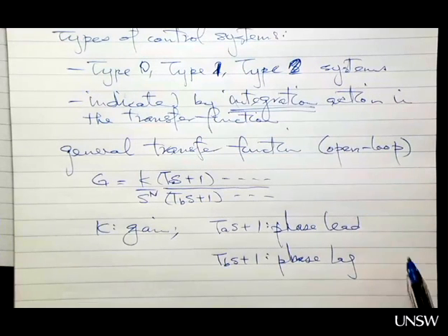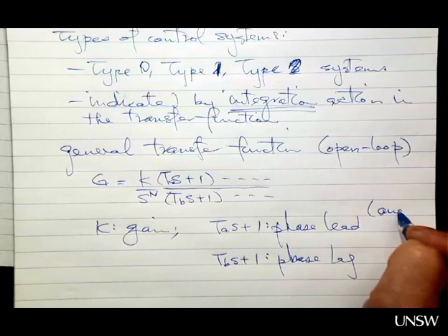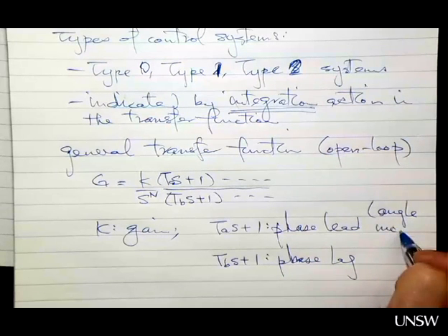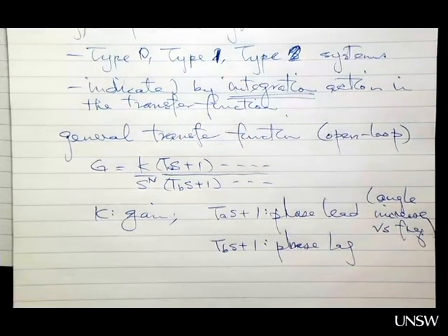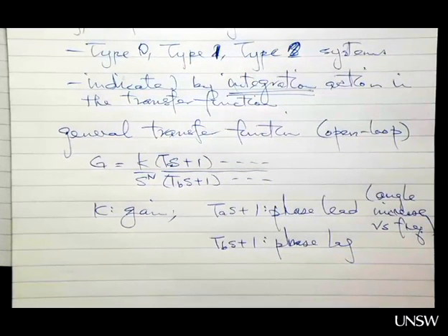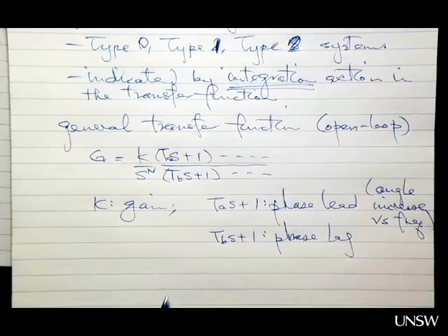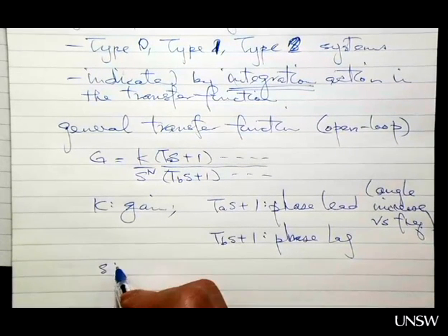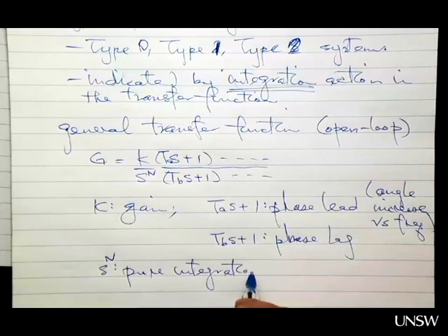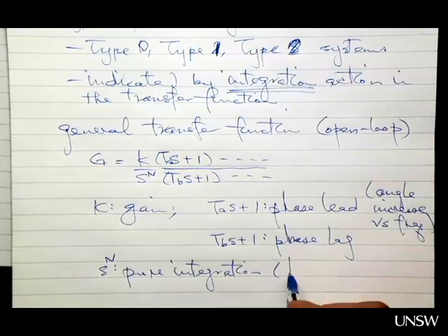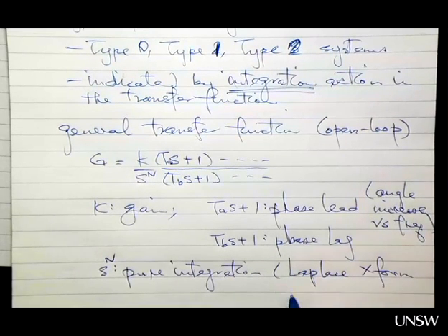The phase lead means that the angle increases against frequency. And then the phase lag is the opposite. The angle will decrease against frequency. And then the S term is the pure integrator or pure integration. So it is from the Laplace transform, the integral theorem.